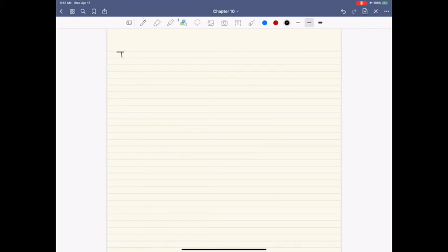So once again, I'm going to write the equation for temperature that we derived: Q dot over M total CV times time plus some T naught. And if we inspect this equation, we'll notice that it basically has the form of a linear equation, right? Where this Q dot over M total CV is a slope, and this thing here is our intercept.